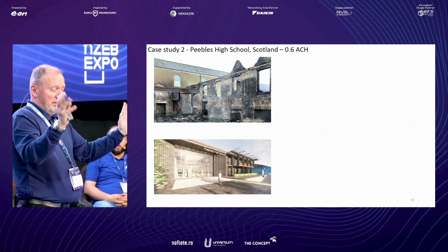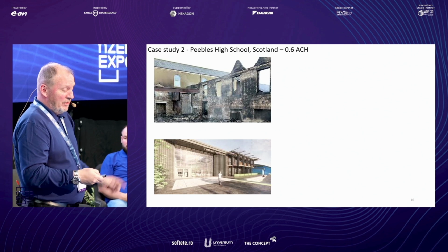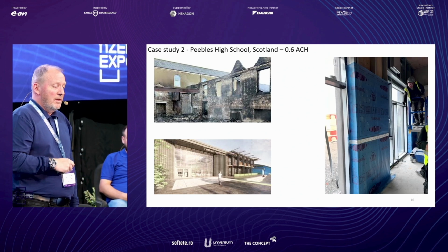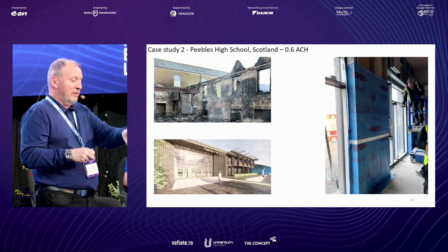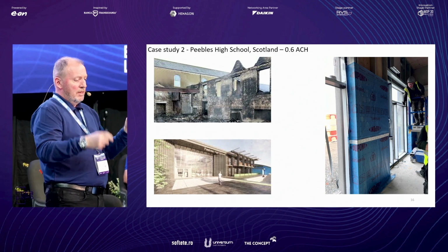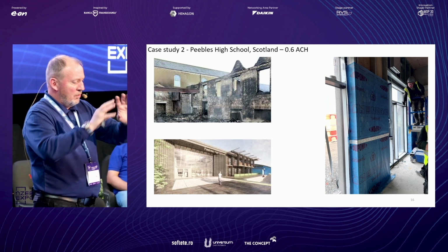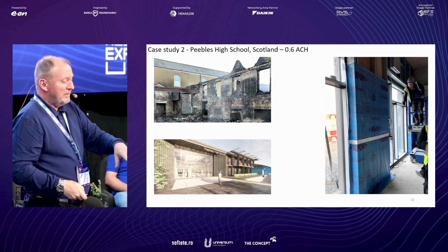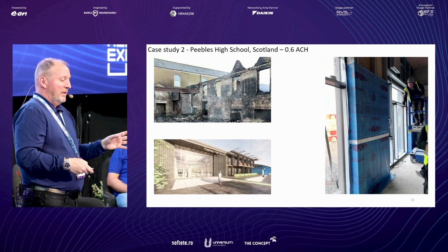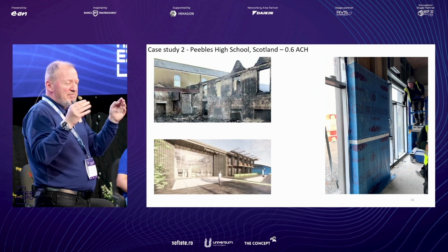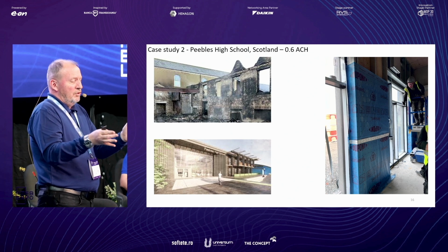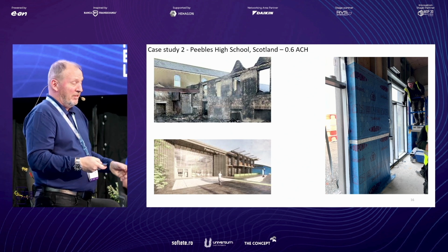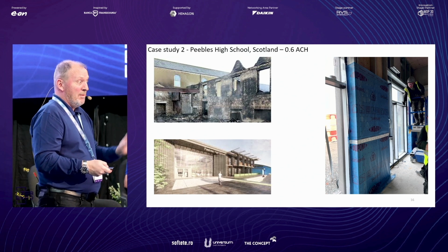Quite nice, nice structure. And we've spent a lot of time on site actually making the building airtight. Now, this section that they conceal with this type of build, quite airy, quite nice, less than 0.6 of an air change. So this particular building will have minimal heat input. 2,000 children running around is more than enough to keep that building warm. I'm absolutely convinced.